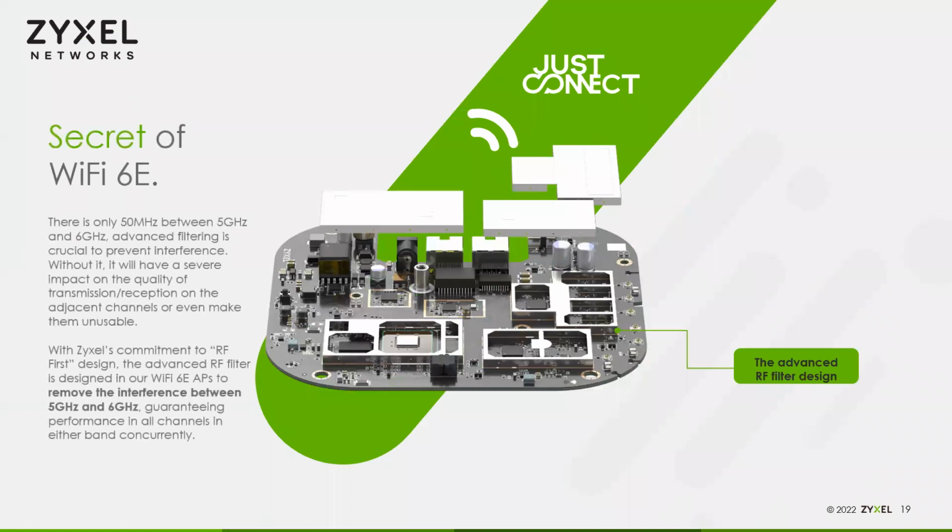And these products continue our general design philosophy when it comes to our business class access points of RF first. So it means lots of shielding, antennas not mounted directly to the PCBA, directly separated, no electrolytic capacitors. And the shielding is especially important when it comes to Wi-Fi 6E, because the 6 gigahertz and 5 gigahertz spectrum only have about 50 megahertz gap between the two. So you do get a lot of band edge overlap between the two. You need that shielding to make sure your 6 gigahertz radio isn't interfering with your 5 gigahertz radio, especially on these tri-radio access points.